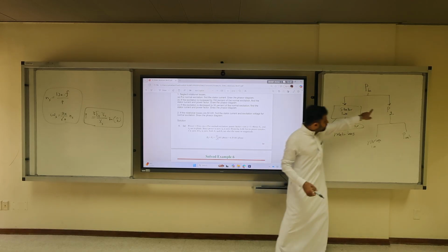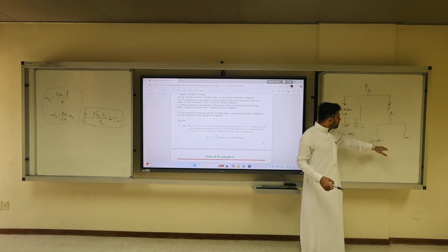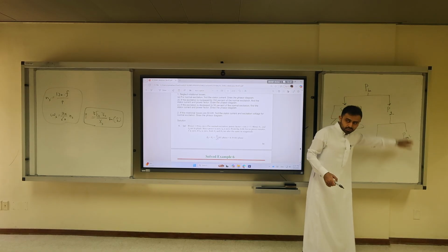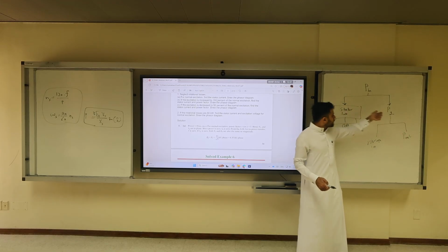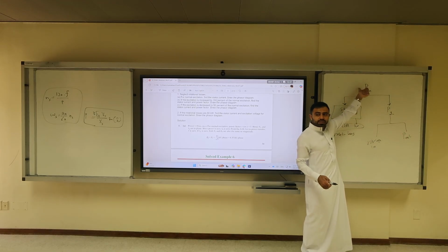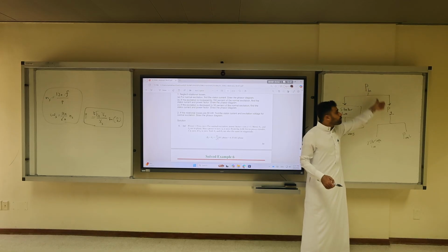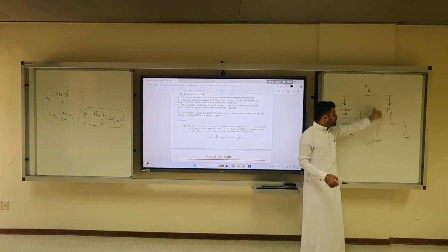It means if my output power is 0, and everything in the rotor side is 0, then in part 1 this is 0 plus 0, so input power is 0. But now input power is not 0. Input power actually equals the rotational losses, because there is no load, so there is no air gap power. Clear?